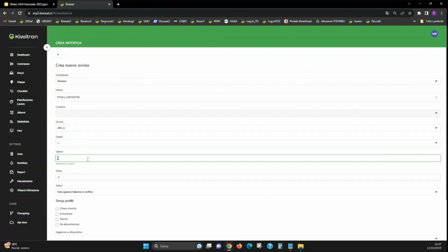Level 0 identifies a no fix. That is, the GPS is not working, or it is disconnected, or it is damaged, or it is simply in a bad position, maybe in a part covered with photovoltaic panels inside the company, or inside a refrigerator cell. It can happen. So, level 0 is not fixed, the sensor can't get the position, so it is not available. Of course, since we can't get the position, we can't block it, so we don't consider level 0.